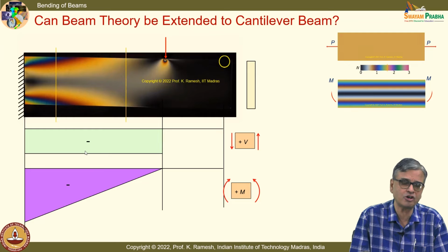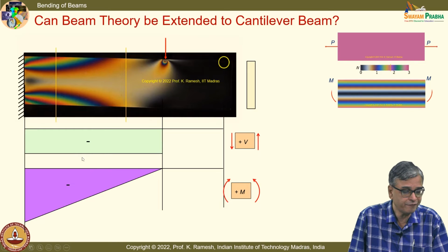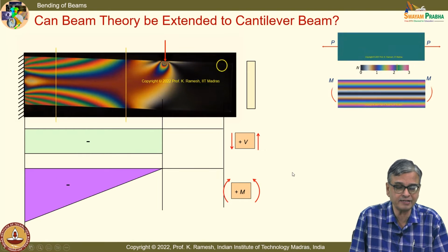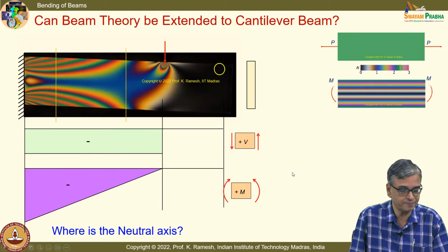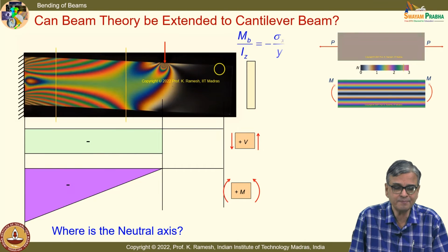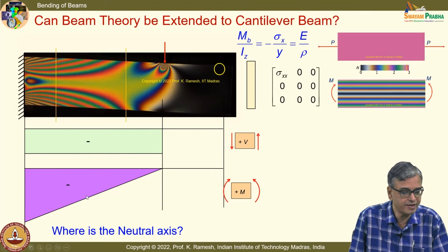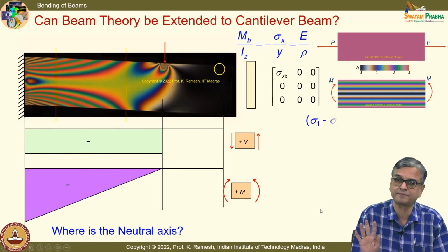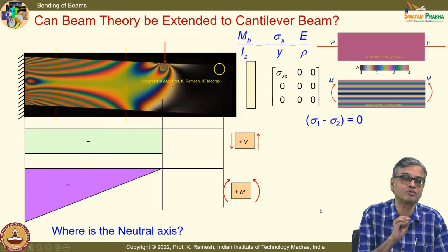Even a simple constant shear modifies the bending moment along the length of the beam. So, the recipe here is you have the flexure formula, and simply pick out the bending moment at this cross section, then find the bending stress using the flexure formula; that is permitted. And we have also seen, even though the cantilever beam warps, there is no coupling between shear and bending